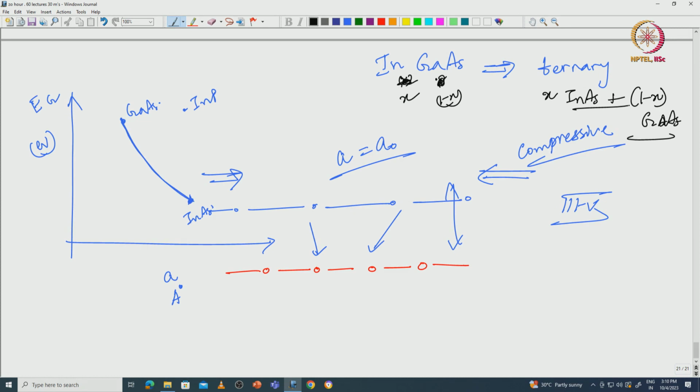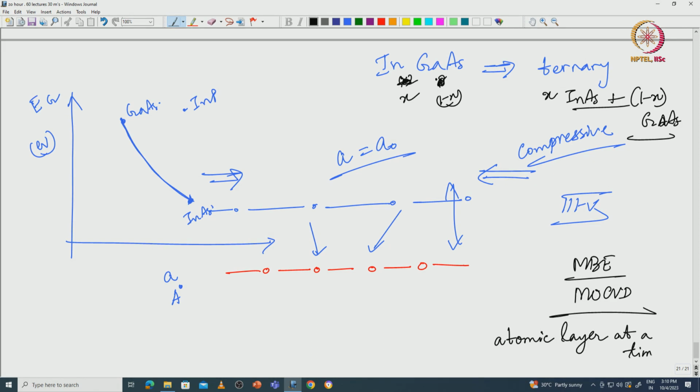and this is grown by these techniques called MBE or MOCVD, metal organic chemical vapor deposition, or molecular beam epitaxy, in which you can grow these layers 1 atomic layer at a time. So the precision is at the level of 1 atomic layer, and that is how you actually get heterojunctions, and that is what enables you to make these high speed HEMT transistors which find application in RF devices. So the whole thing is fairly involved.